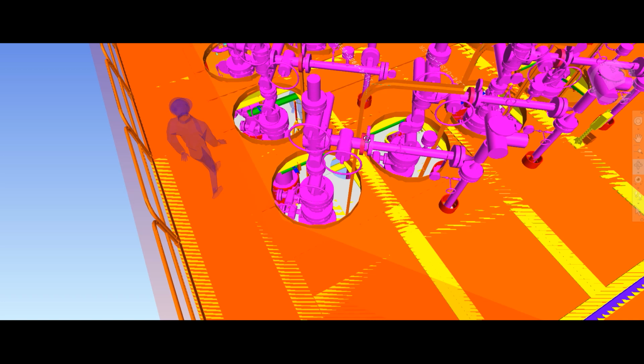From this wing valve we have a spectacle blind, and then we have a flange which is connected with the wing valve. Then we have the pressure indicator, then we have the thermo valves. Up to this, normally we keep the API spool to connect with the API rating, and sometimes the API rating is matching with the ASME rating. Up to 5,000 API rating, it is matching with the ASME rating, but 10,000 doesn't match with any ASME rating. So we have to use an adapter spool, where one side is API rating, other side is ASME rating.